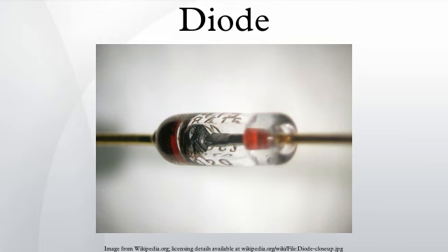A thermionic diode is a thermionic valve device, consisting of a sealed evacuated glass envelope containing two electrodes, a cathode heated by a filament, and a plate. Early examples were fairly similar in appearance to incandescent light bulbs. In operation, a separate current through the filament, a high-resistance wire made of nichrome, heats the cathode red-hot, causing it to release electrons into the vacuum, a process called thermionic emission. The cathode is coated with oxides of alkaline earth metals such as barium and strontium oxides, which have a low work function, to increase the number of electrons emitted.